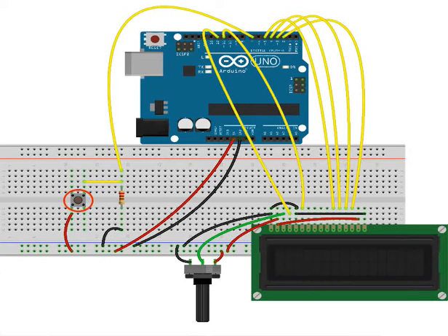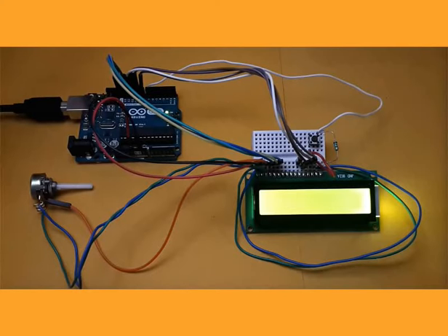Here we will add a push button and make a simple counter. We have already learnt about the working of push button in an earlier tutorial. Now let us learn the connection circuit details. A push button is connected to a 100 ohm resistor. The push button is connected to pin number 7 and a 100 ohm resistor is connected to the ground. All other connections are exactly the same as in our previous experiment. This is the live setup of the connection, as shown in the circuit diagram.